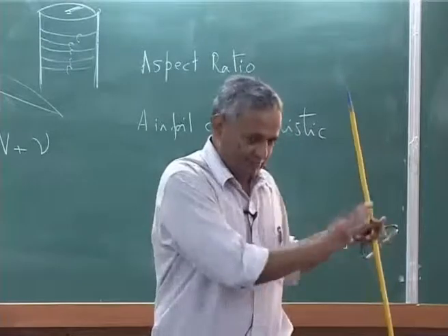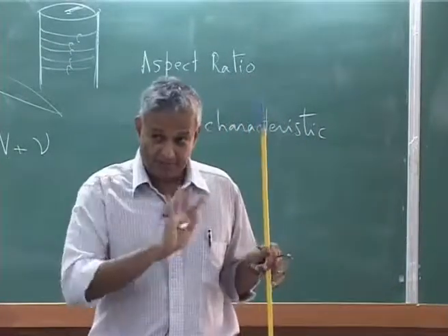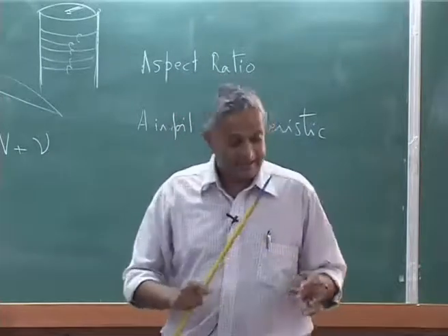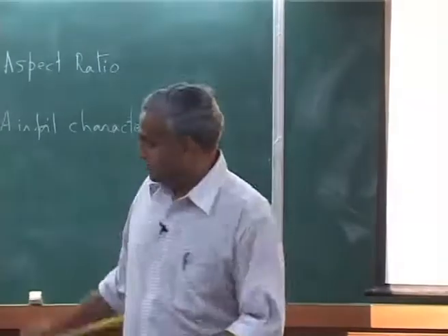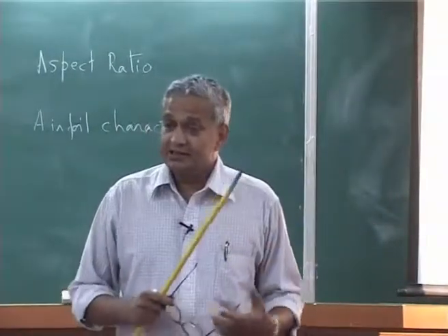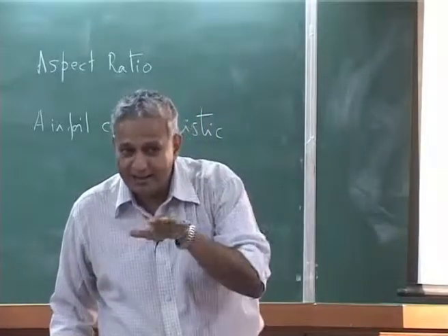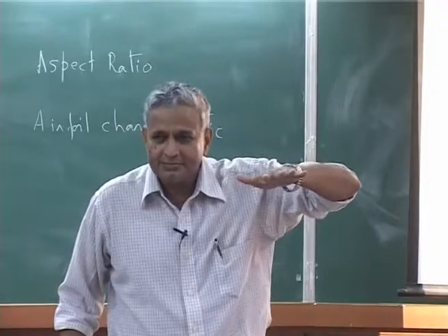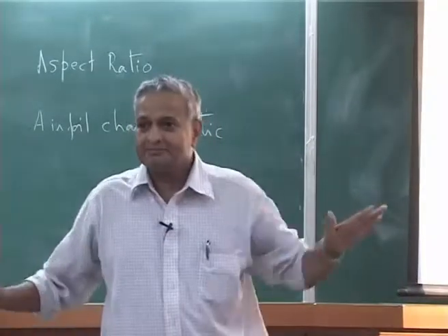There is one theory which is a dynamic wake theory, which is somewhat similar to this. Please understand that dynamic wake is the model we use. We do not model this, we use another theory to get the time varying inflow at the rotor disc. Till now we used constant inflow, it does not vary with time, constant and uniform everywhere.